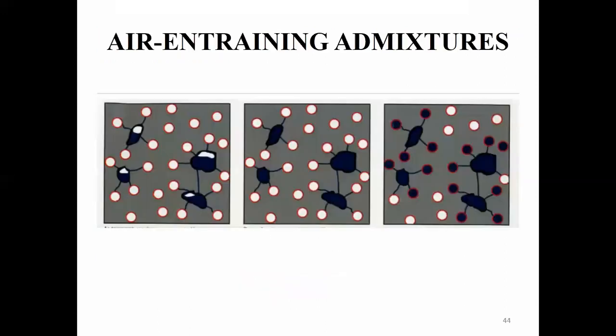Here, this diagram we have discussed. I repeat it once more, because this is the important mechanism. See, here you have your crack. Let me explain. Here you have some of the air entrained. These are the air you have entrained yourself. See, these cracks are interconnected. But these cracks are also interconnected to the air bubbles.